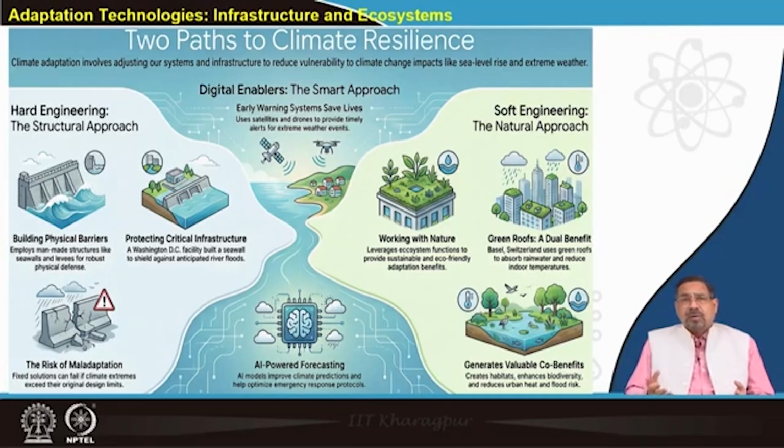In terms of porous areas, structures and systems along and across the city space, there are also co-benefits when we retain wetlands or low-lying areas. That gives a buffer in terms of cooling off, and in terms of floods or flash floods around and across the habitations or our landscape. So this soft engineering or natural approach falls under nature-based solutions.